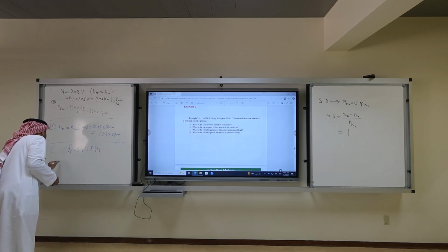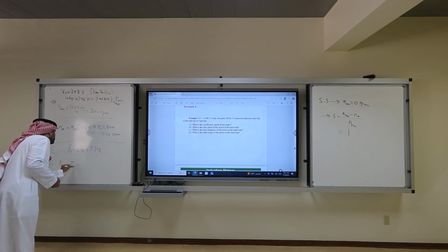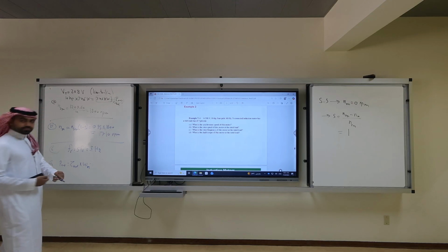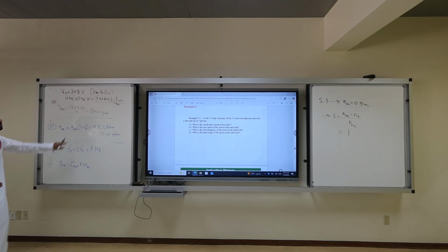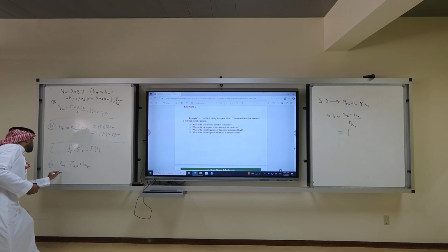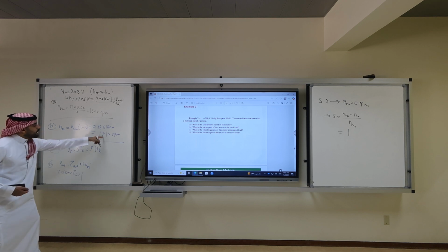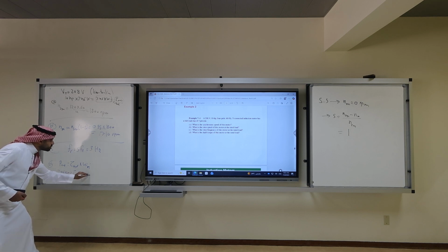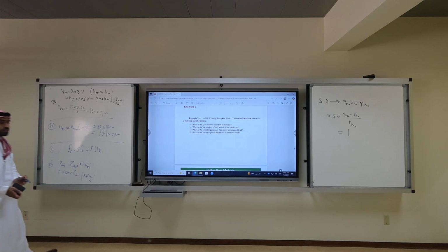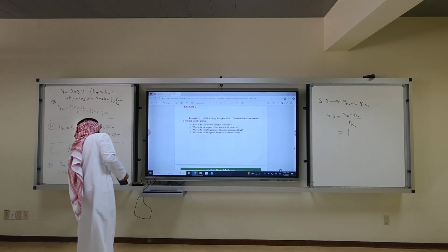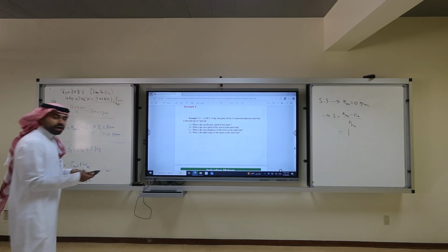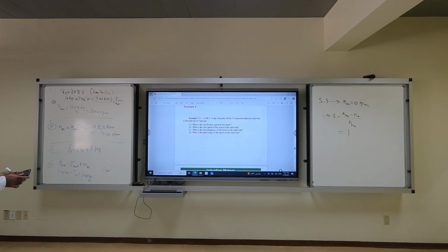You do shaft torque: from output power, it is torque of the shaft times omega m. What is the output power? 7.46 kilowatt equal shaft. Now what is omega m? 1710 times 2 pi over 60. So what is the output torque? Calculators. 41.7. You're right.